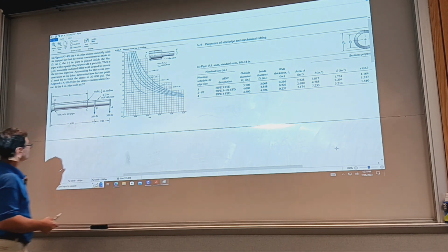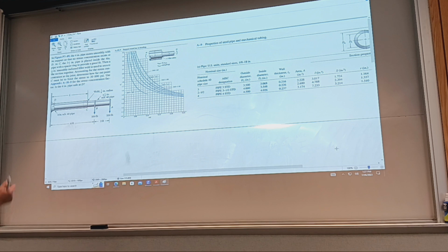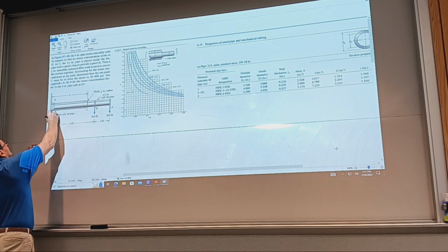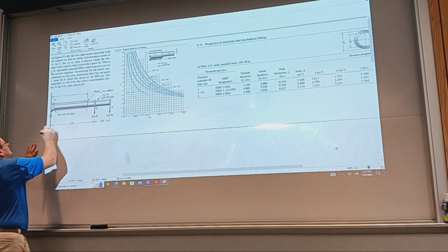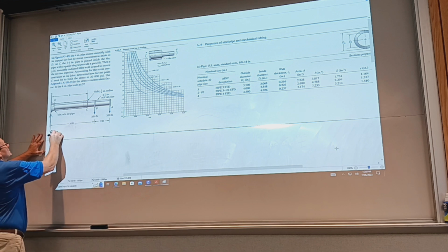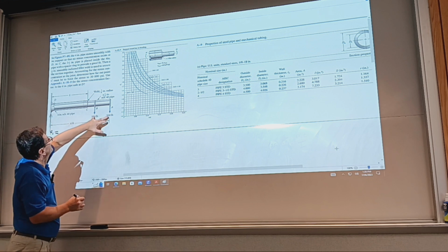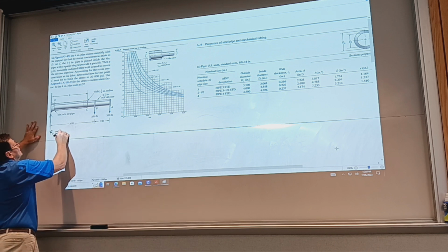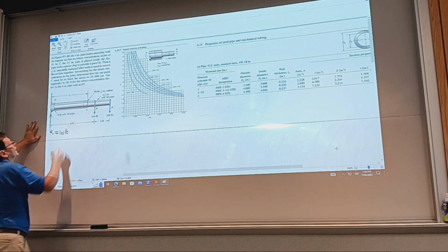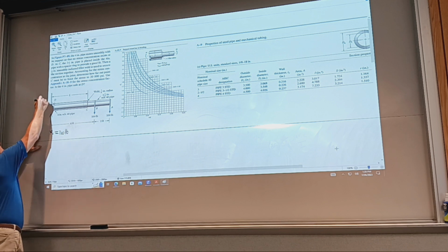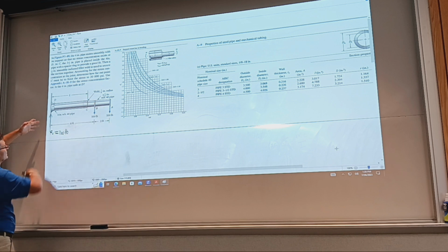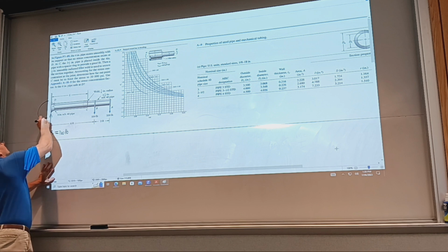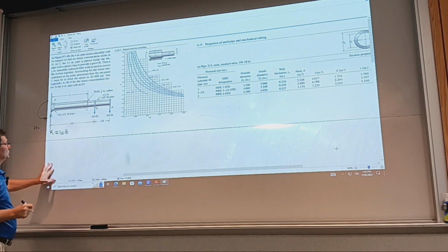Yeah, it's what is required. So we're having a cantilever, and there is a reaction A, and we can tell right away. So the reaction at D is going to be these two forces combined. So 700 pounds. And then there's a moment. The pipe wants to, or the assembly cantilever wants to go this way. I need to apply a moment that goes this way, counterclockwise, M. What is M equal to?